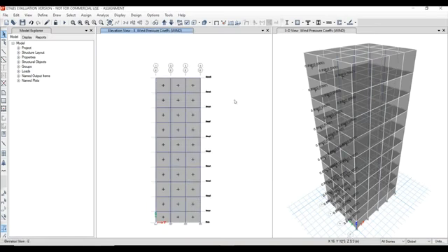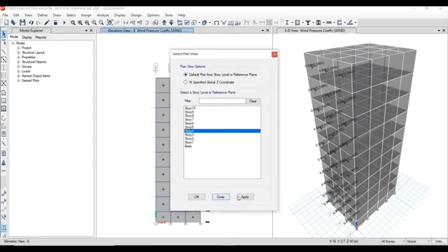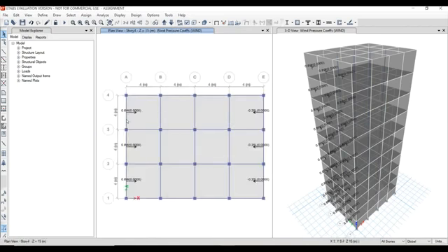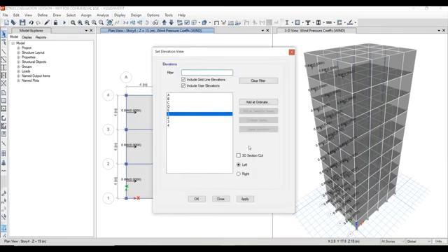OK. Now go to a plan view of any one story. Click OK. Now we have added windward direction and leeward direction. We need to add for sidewards. For that we need to have sections of 1 and 4. So go to elevation of 1. OK.